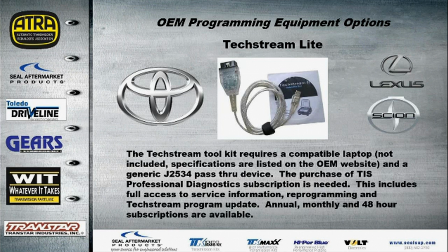Toyota, TechStream Lite. Now, Toyota has two different programs. I'm introducing here the limited program, or the Lite program, which is basically going to service everything that has OBD2 and later. Now, with Toyota, they give you the software, and then they recommend to bring your own J2534 pass-through device. So pretty much they give you a litany of pass-through devices to choose from. The one that they recommend and they've tested extensively was the DrewTech Mongoose.